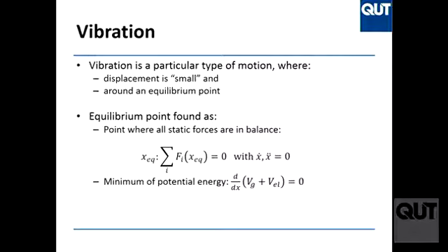If you have a building that vibrates, a tall building. Okay? How much will a building vibrate? What do you think? Let's say one William Street, the tall building. How much do you think it will vibrate on the top? A building like that. Order of magnitude. Okay. Millimeters, centimeter, meter, kilometers. I'm talking about the vibration amplitude. Meter. Okay? So the vibration amplitude is actually a meter for this kind of building.